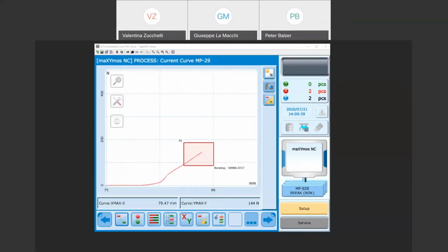Okay, so now this time with the right program. Brake, okay, without any tare elements. So you see bending is detected of 224. It's below 1000, so nothing is happening. So you can use this window, for example, or this evaluation object, if you want to make sure that your tool is not broken, your part is not broken, or anything else is happening during the process. Well, you should use it where it makes sense, of course.